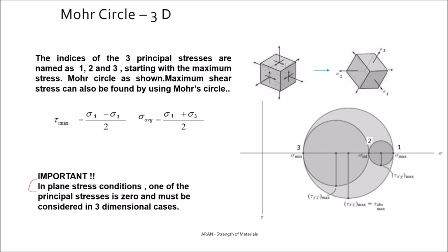The in-plane stress conditions, two-dimensional cases, which we have considered up to now, can be seen as a three-dimensional case, but a special three-dimensional case where one of the principal stresses is 0.